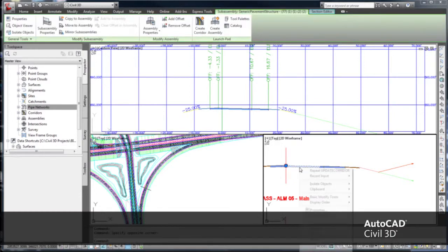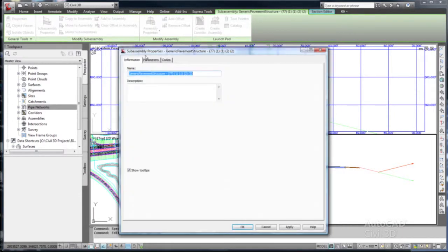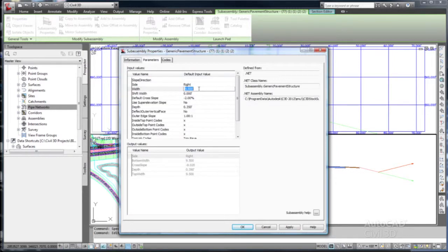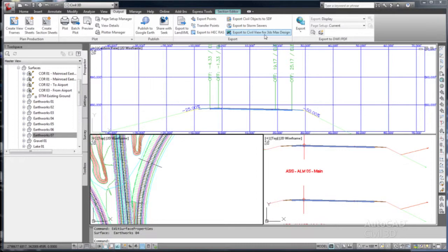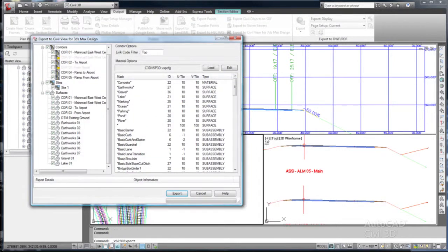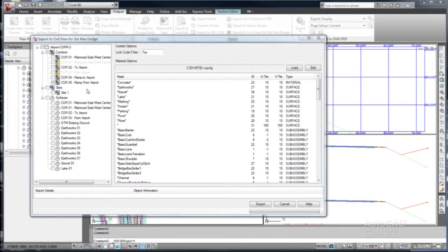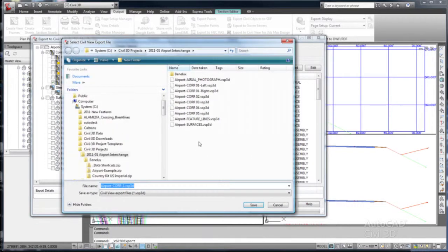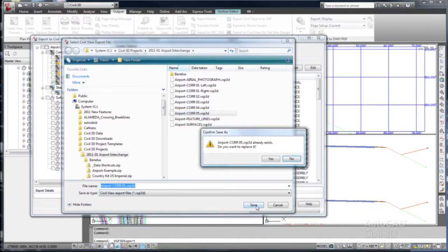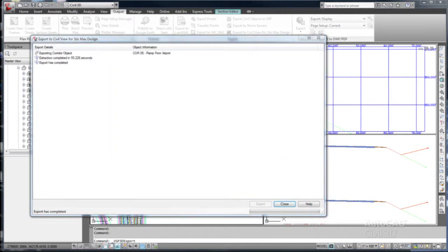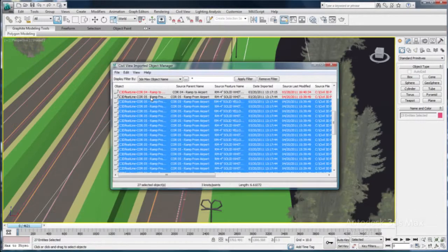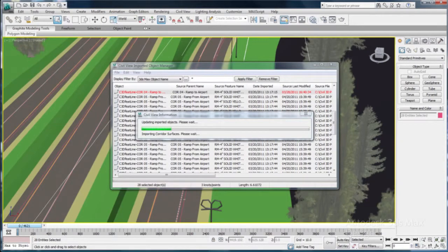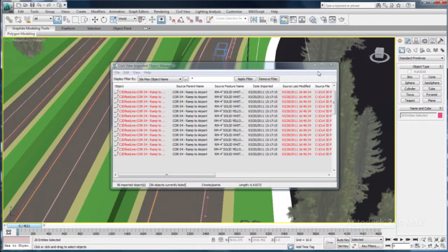Using the Autodesk workflow, Civil View imported elements retain a permanent reference back to any imported Civil View VSP exporter files from which Civil 3D content has been derived. This means that as the project evolves and the design model is refined, design changes can be easily incorporated into the existing visualization. For example, if you update a portion of the Civil 3D model, you can simply re-export the model, overwriting the original VSP exporter file. In 3ds Max Design, you can choose to import only those objects that have changed. The dependencies built in result in an update to all related content as well.